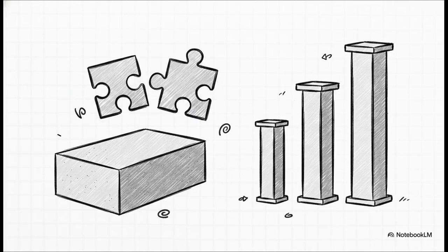Okay, let's put the pieces of the puzzle together. The formula becomes crystal clear once you see it. An M20 mix simply means that after 28 days of proper curing, that concrete is guaranteed to have a compressive strength of 20 megapascals. Boom. M25 gives you 25 megapascals, and M30, you guessed it, a solid 30 megapascals. It is such a beautifully logical system once you know how to read it. That number is literally telling you exactly how strong your foundation is.